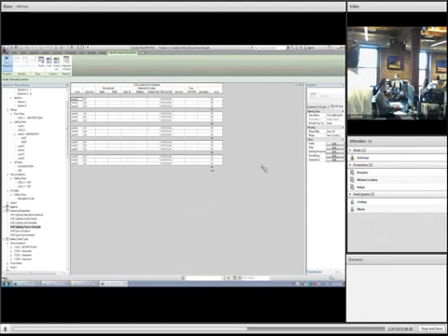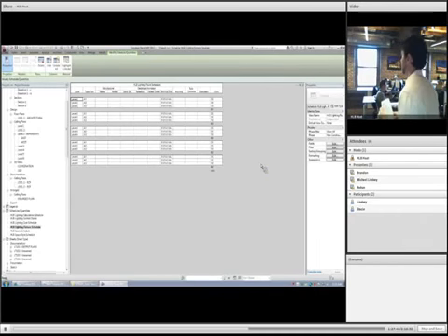I'll give my caveat with that one when we get there. That sorting grouping parameter, or the way that you sort and group a schedule, there are so many possibilities. Obviously, it's really endless. Does this help give you a window into the data side, maybe a bit more? And seeing the parameters that are being pulled by lighting fixtures, and then also simply you can just add a piece of data to a model category quickly. We did it through a schedule. Because that was a lighting fixture schedule, that's why we're able to do this.